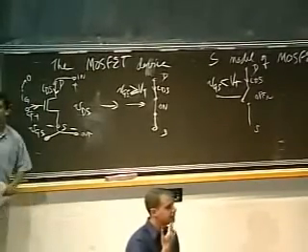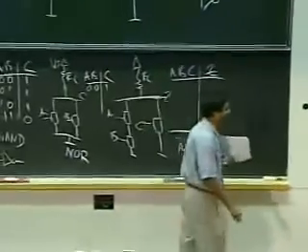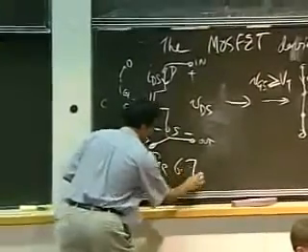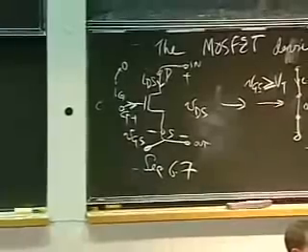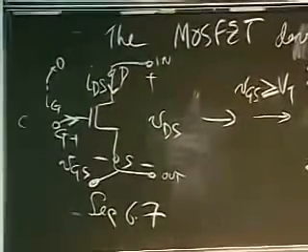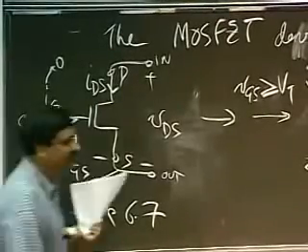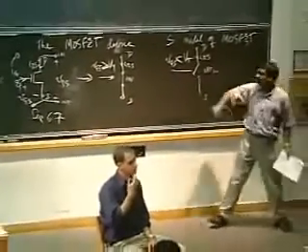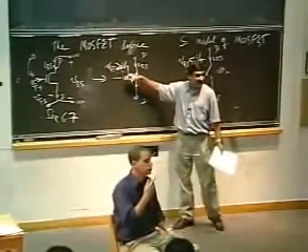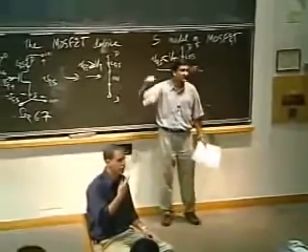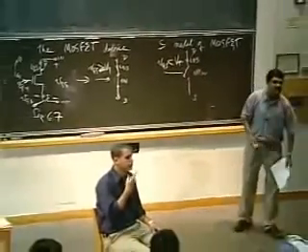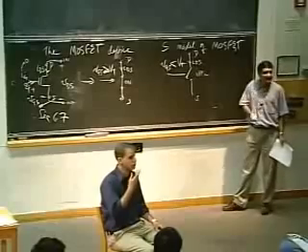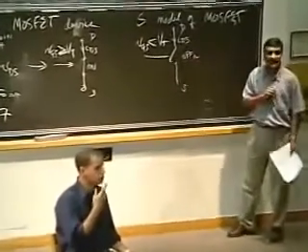If you want to see the internals of the MOSFET, I won't cover that in lecture or recitation. You can look at the section, I believe, section 6.7 of the course notes. Okay, that has the internal structure of the MOSFET and how you physically construct such a device. So what I can do here, step back and stare at the device for a second or two, and what it says is that if I apply a lot of pressure, if VGS is greater than a threshold VT, then I get a short circuit here. Just like my switch, when in doubt, think faucet. When you put pressure on the faucet, think of this as closing, and when I open it, when VGS goes less than VT, less than a threshold, I take off the pressure, then it becomes an open circuit.